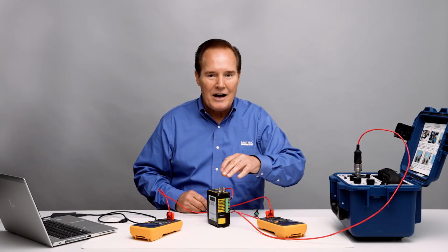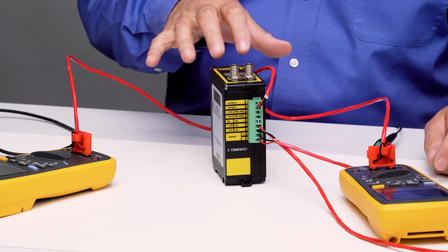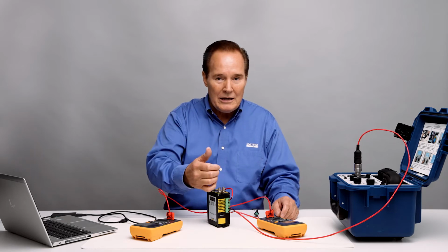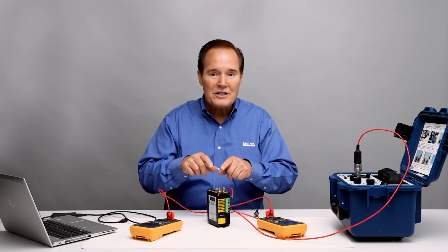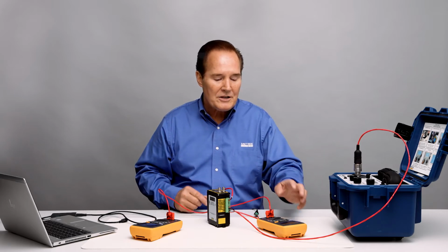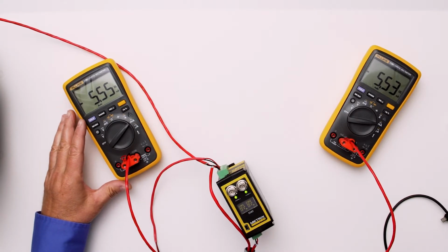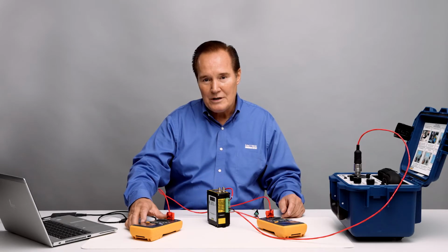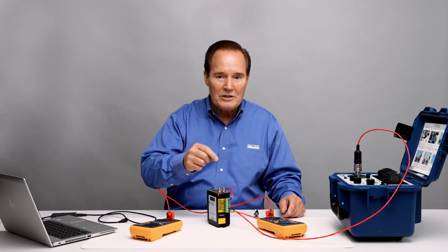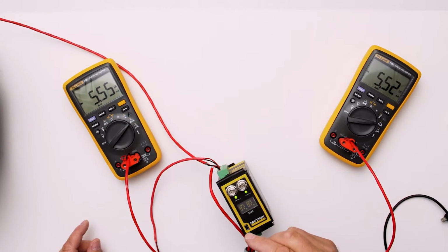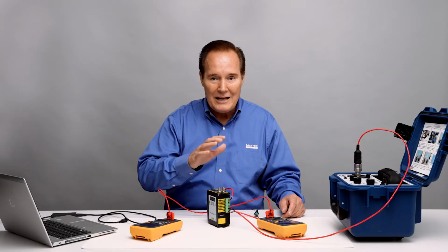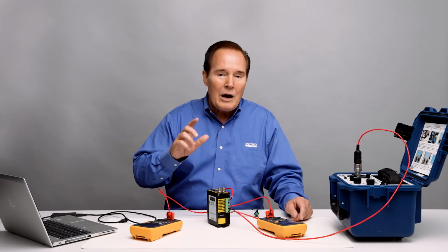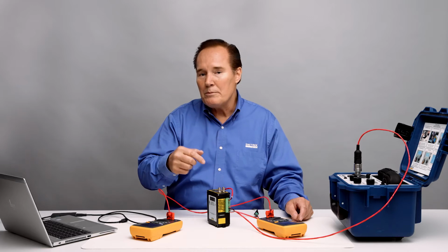I'm taking data inside. How I have this 5580 set up is in a dual path mode, where I have one channel coming in and I have it separated as two acceleration channels coming out. So I have acceleration out of channel 1 in milliamps. This is channel 1 to my left, and I have channel 2 to my right in milliamps. Now, if I was measuring the raw signal in either channel in this mode, I would be measuring acceleration, no matter what I'm doing in this experiment, the way I've got this set up. What I want to do is change channel 2 into an impact measurement.